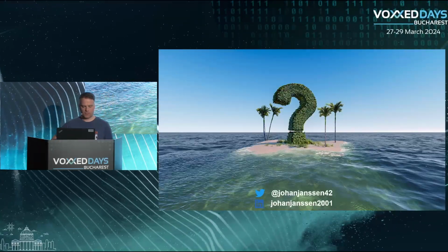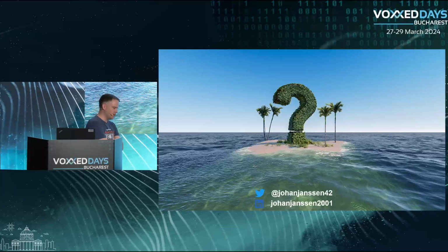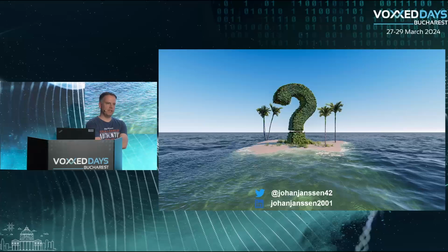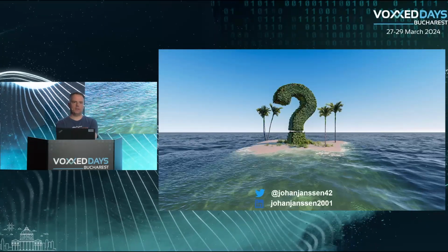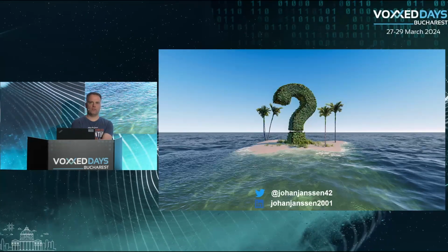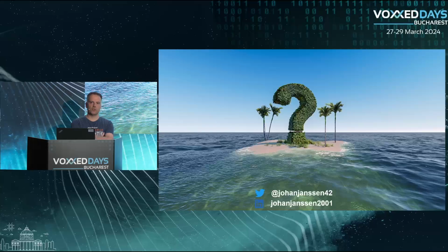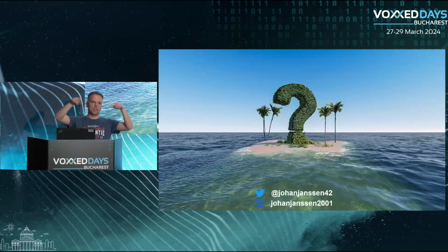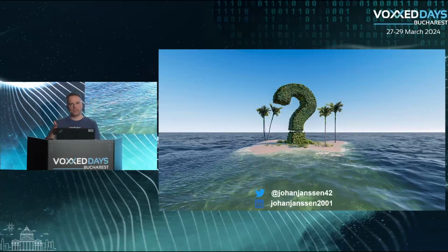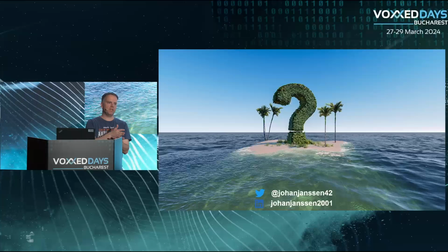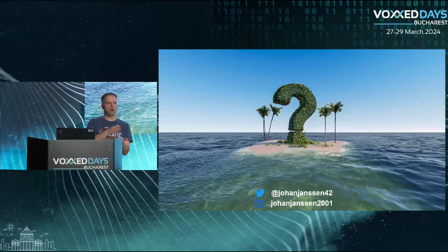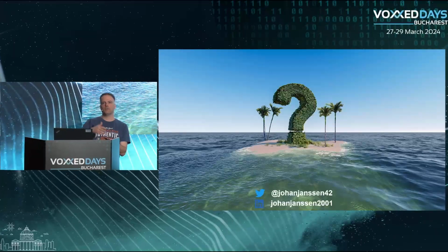Rectangle. Because it's a good question. So why are wafers round and not rectangle? The chip is rectangle, indeed. Maybe you can cut the losses on the edges. I think it has to do shortly with the printing, and also probably if something is a square, it's more brittle. The edges could break and things like that. So they actually did a lot of tests. Also for wafers, if you look at the history, they started with, I think, 10 or 15 centimeter wafers in diameter. Now most use 30 centimeters, but there are even some that are bigger.